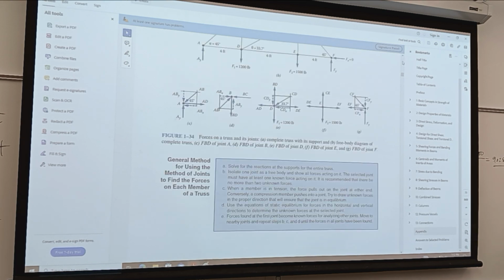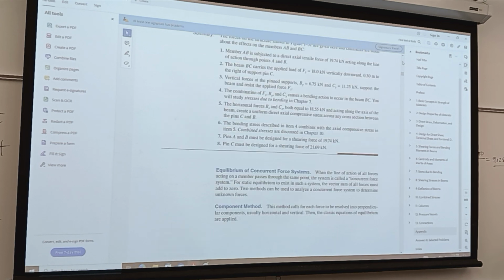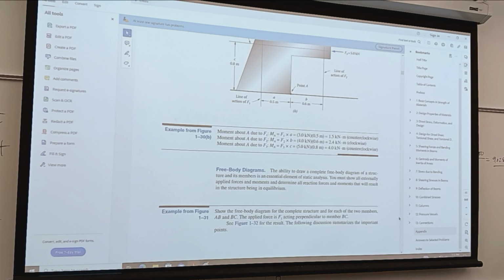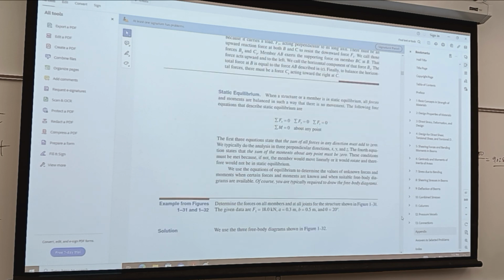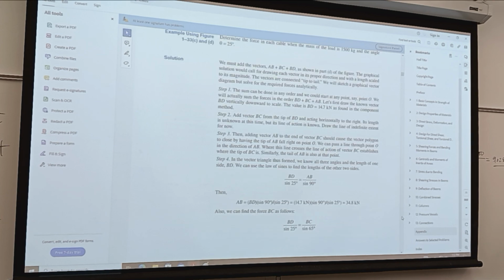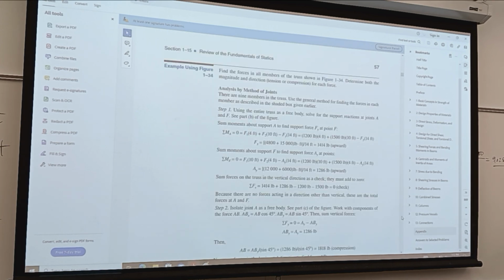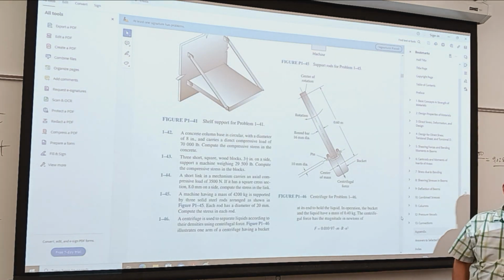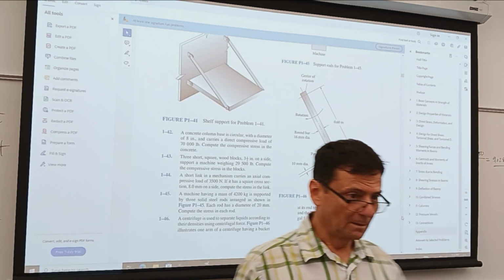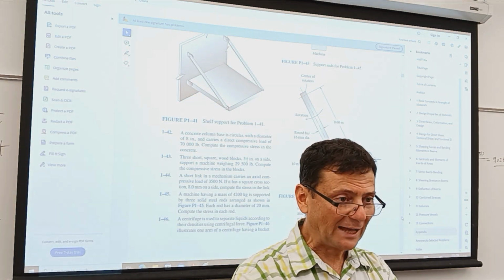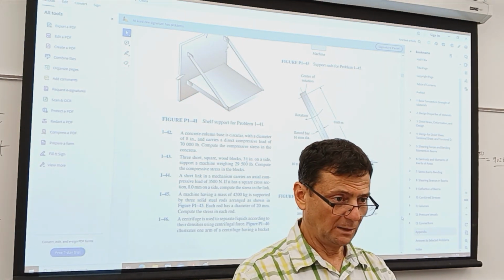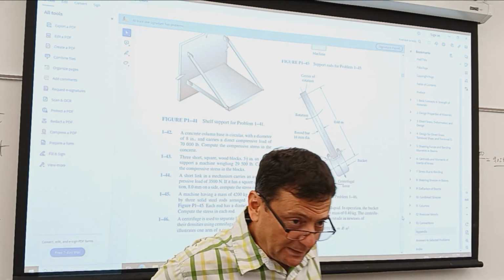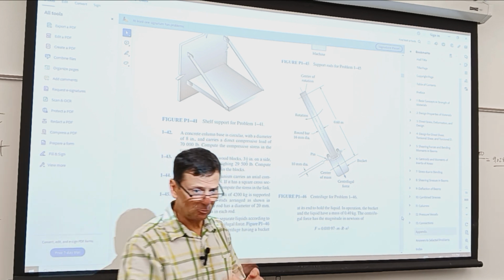In the aerospace industry, because they want to save on weight, they go with design factors that you don't find in general machine design. But what they do instead, they have periodic checks, and they also have more stringent requirements upon the properties of the material. So a batch of, say, aluminum sections for the wings, they want to know the certificate for that batch. What is the yield strength? What is the ultimate strength?